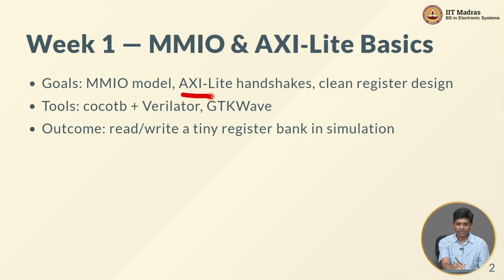We will be talking quite a bit about the handshaking protocols used in the AXI-lite bus interface and talk a little bit about how registers can be implemented. So, I will actually be showing you Verilog code corresponding to a register bank and how we can set up the AXI bus in such a way that we can read and write the registers that are present in that bank.